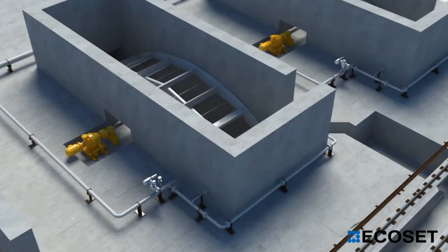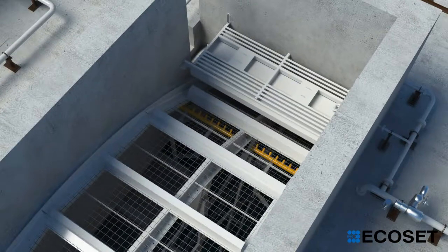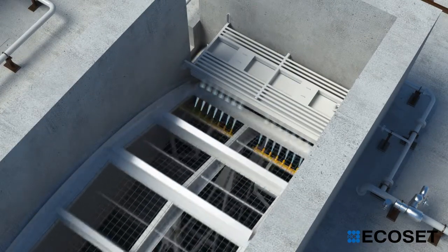With the initial startup method of the drum screen, the washing water flows into drum screen when the spray washing pump is started and MOV is opened. If the pressure of washing water reaches the set pressure, drum screen is activated.